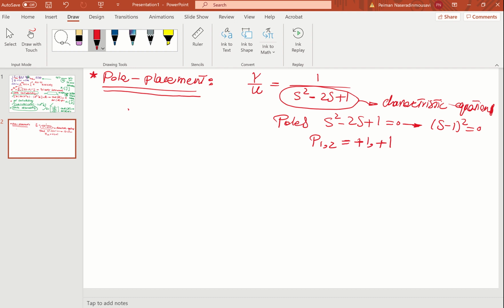That's right. And if you remember from undergraduate control, you know that if you have such positive poles and I plot in the S-plane, for those of you who forgot, this is the imaginary axis, this is the real axis. We know that this area is the area of instability.